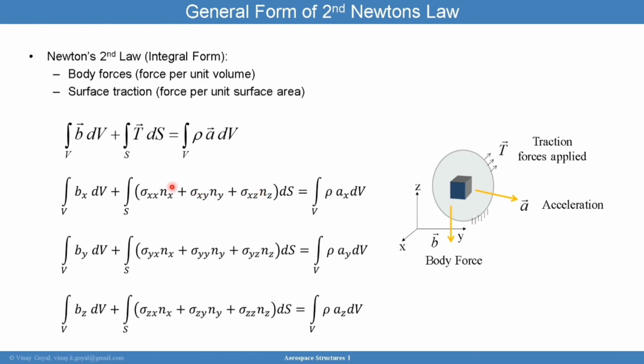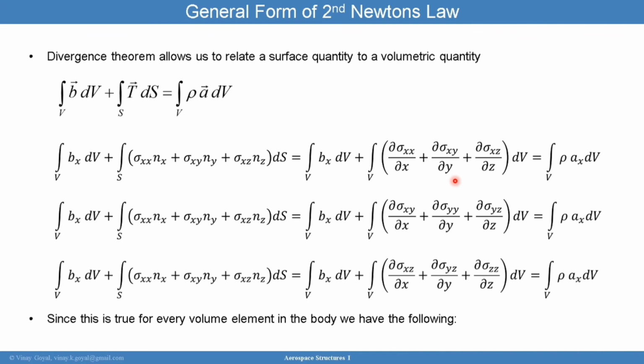And now the next step is, so what again, because this is a volume quantity, and this is a surface integral. So this integral is only on the surface, and stress is something I want to be able to tell as a point-wise quantity. Right now, this is only on the surface, but I really want to relate it to stuff going on inside the body, because that's where the body could fail. And so to do that, I have to use the divergence theorem.